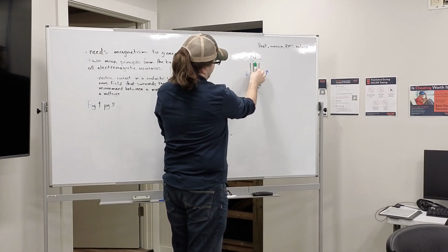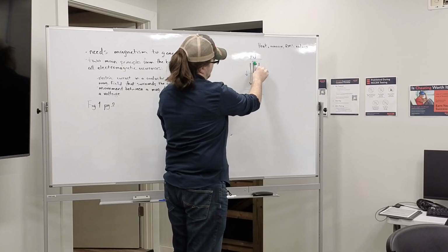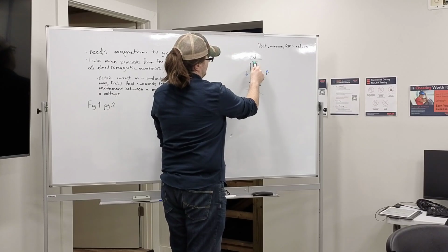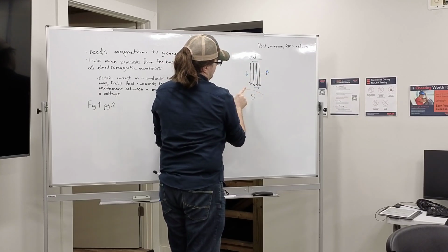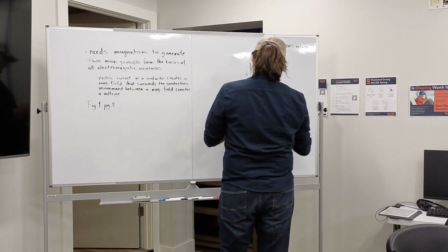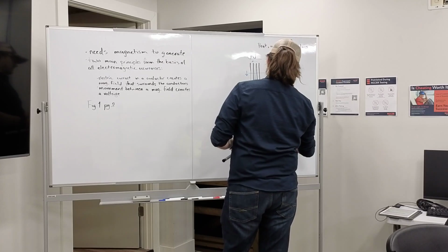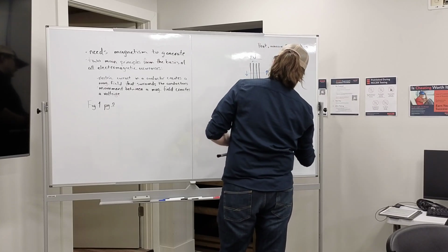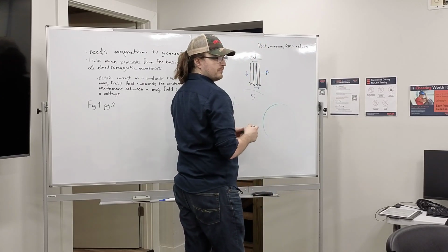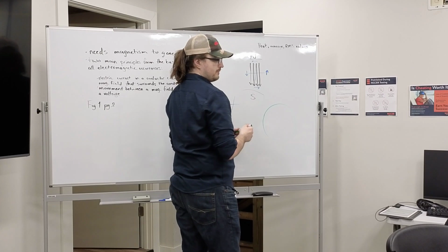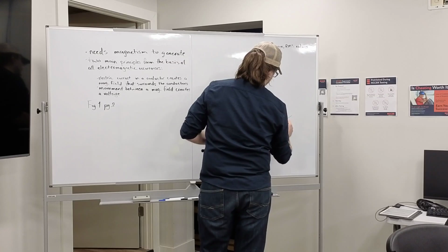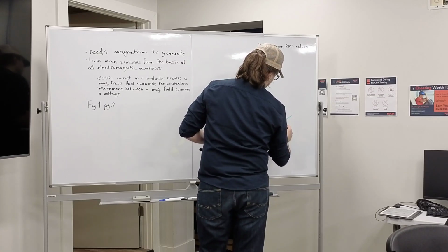Because it's spinning, when it's up here, it's going to spin this way, which means at this point, the movement of that conductor is here and here. Whenever the conductor is horizontal, on your graph, that's at 0. And the speed at which that is spinning, that's your frequency, right?